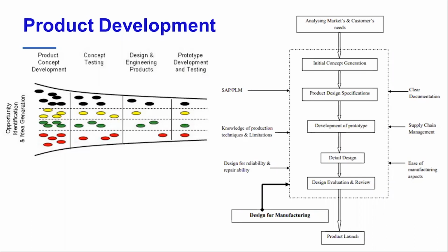If I want the tank to sustain all the temperature zones, all the vibration levels, all the G loads, I need to have certain features. Typically tanks are made of plastic, so I have to have this thickness at this location, and this rib here, this stiffness member here, this type of bracket, the way the tank is mounted to the chassis.